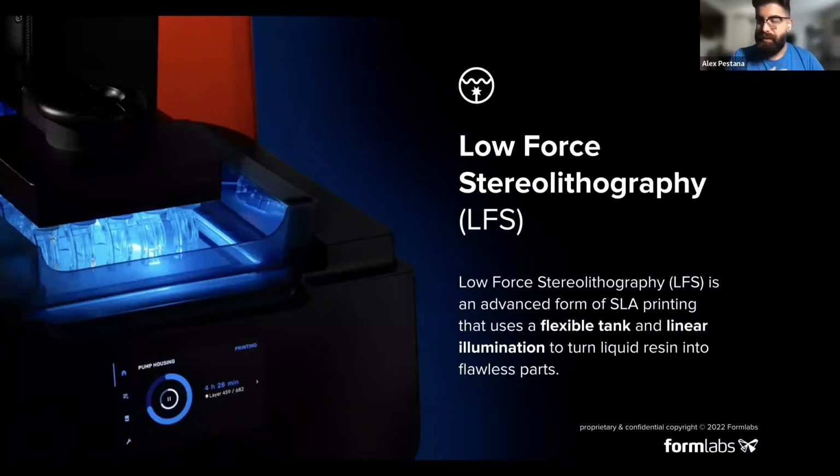With traditional SLA, you have to make sure you clean the mirrors, make sure the galvos are calibrated. So any miss or any speck of dust could bend the light in a certain way and create some problems. So we integrated that into one unit. And the flexible tank just allows for a lower peel force, so that separation force between the bottom of the tank and the part is a low force in our situation due to that flexible tank. So it helps increase part reliability, print reliability, while still being able to use all the same resins that you've been using on Form 2s and before.